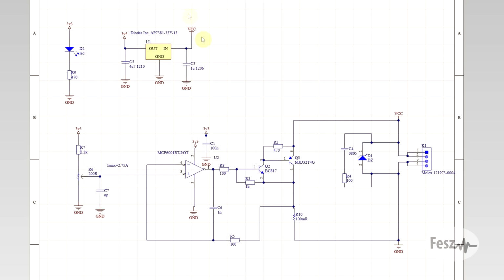So I used a 3.3 volt LDO in all of the schematics. The 1.8 volt version was not in stock. And then I also added in a basic indicator LED, just to show that the circuit is powered. Now, it is true that the LED supplied at 1.8 volts would have difficulty turning on. But anyway. Now, at the right side we have our connector, and here there are two noteworthy elements to mention.